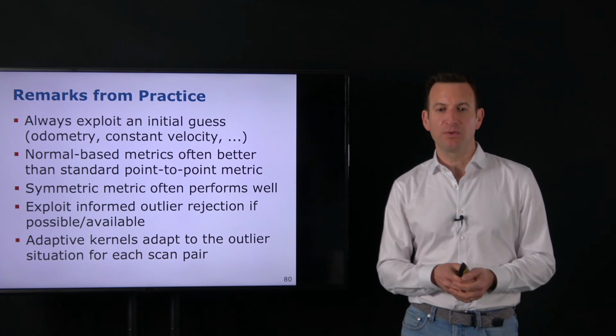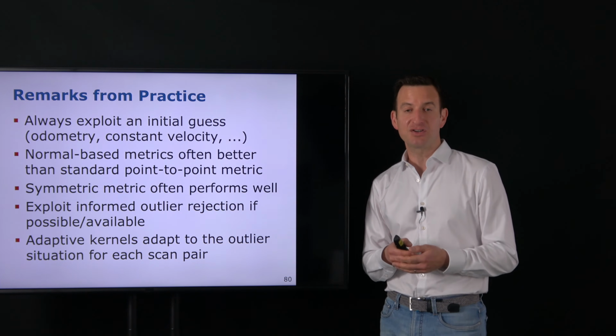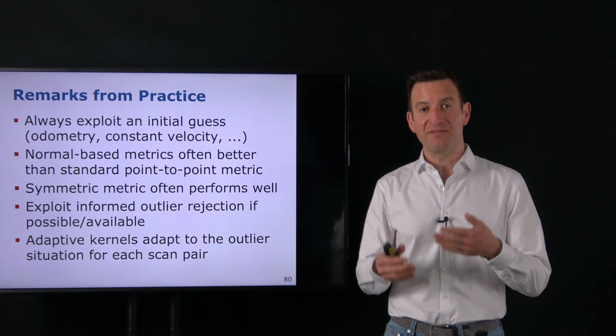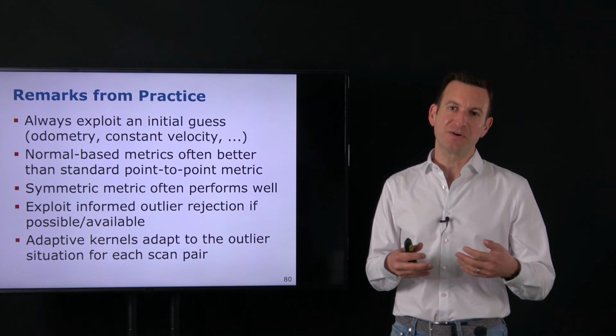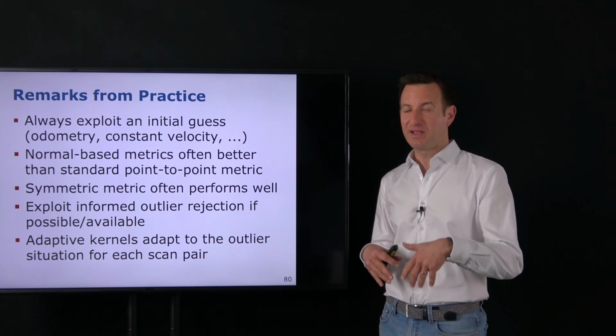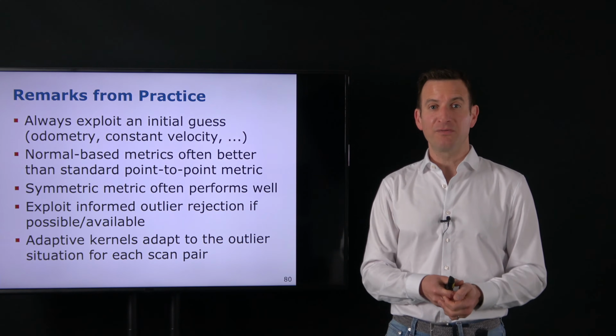You should always exploit your initial guess if you have an initial guess. So this is one of the recommendations. Never ignore an initial guess that you have. This initial guess will be valuable for you because it probably gives you a better data association in the first place, and then your registration algorithms will perform better.